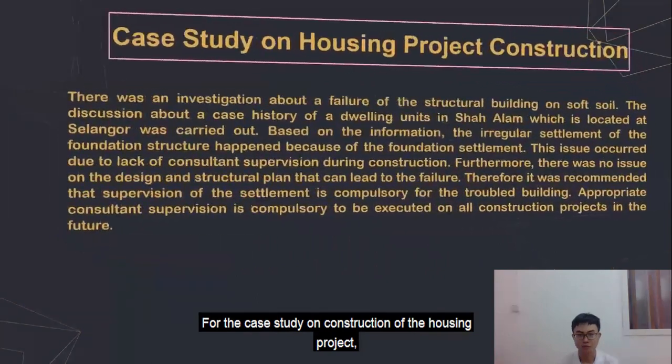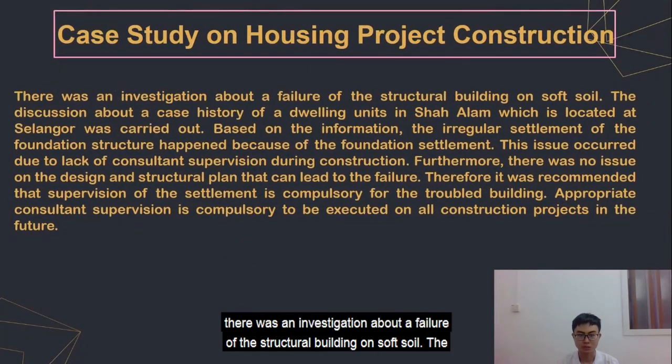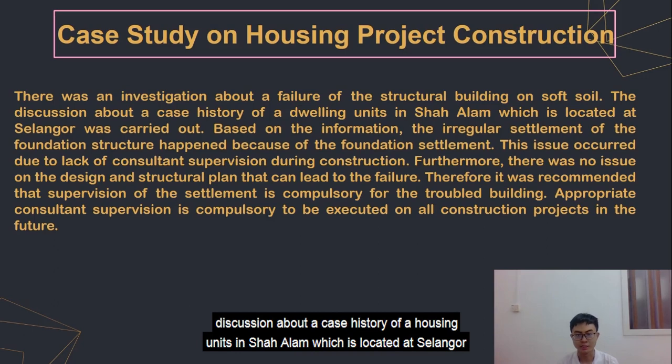For the case study on construction of the housing project, there was an investigation about a failure of a structural building on soft soil. A case history of a housing unit in Shah Alam, Selangor, was discussed. Based on the information, irregular settlement of the foundation structure happened because of foundation settlement. This issue occurred due to lack of consultant supervision during construction.